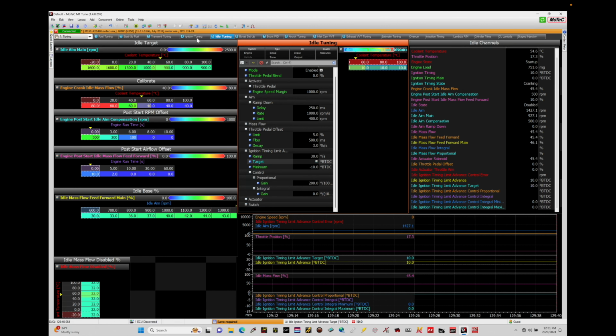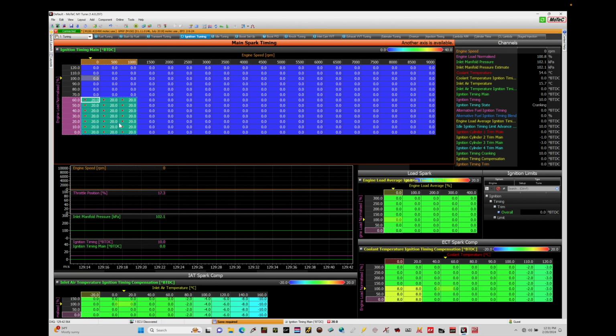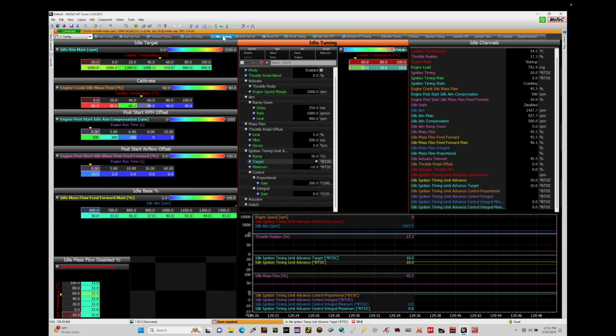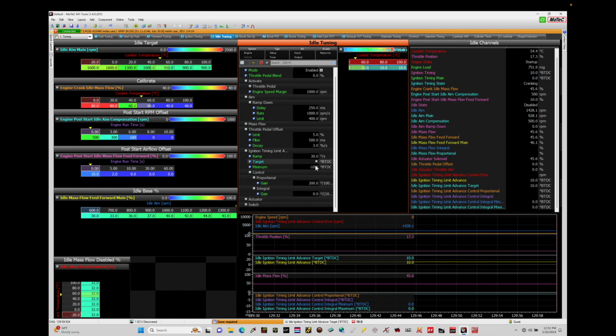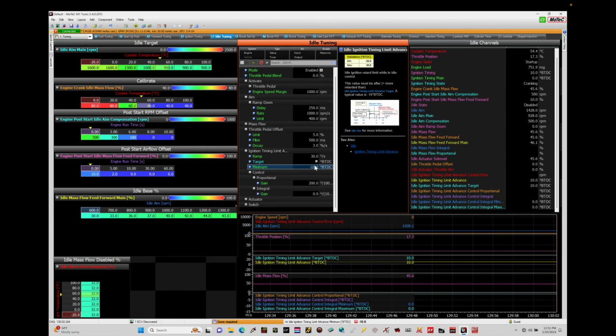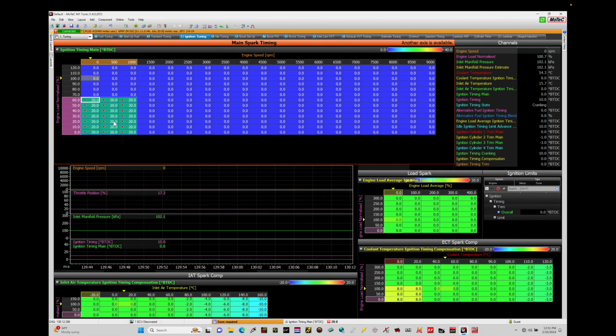The ignition timing table, what we have in the ignition area here, that's going to be the high adjustment point or the ceiling of where we can adjust our ignition timing to. So we want to have this at least 5 to 10 degrees higher than what we're calling out for in our idle ignition trims. That's going to be where it starts the adjustment from. It's able to then add up to what we specify here in our table. It's then also able to reduce down in spark timing to what we command here as the minimum. So essentially we have about a 10-degree adjustment we're allowing the ignition timing to make, actually about a 20-degree adjustment here if we go to the minimum. But either way, we have a ceiling and a floor, and ignition timing right here at idle should be our ceiling or the highest we want to run it at. So 20 degrees is fine.